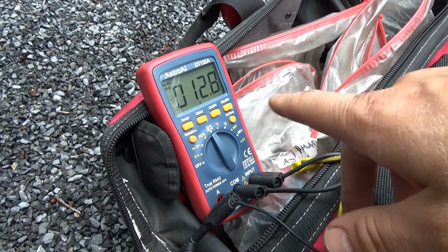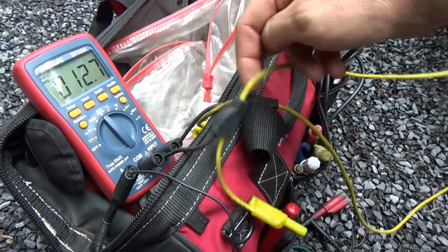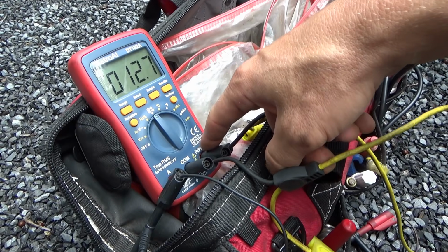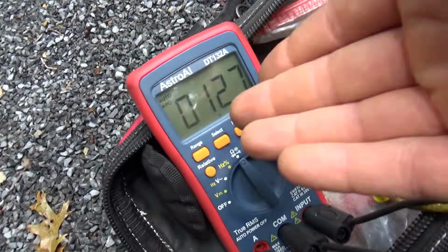Alright, so first thing I want to do is check the resistance through the compressor, through the valve. So on this lead, the black one is coming into this port, the input, and the COM is just a ground. So I have this other lead, just the black wire attached to the body ground. So, about 12 ohms, that's reasonable. So at full blast, at 100%, this valve should draw about 1 amp. Keep that in mind. Now, the controller is saying, hey, there's a short circuit on this wire. So what I want to do is substitute a smaller load on that wire, like 300 milliamps, and see if the controller is capable of turning that on.